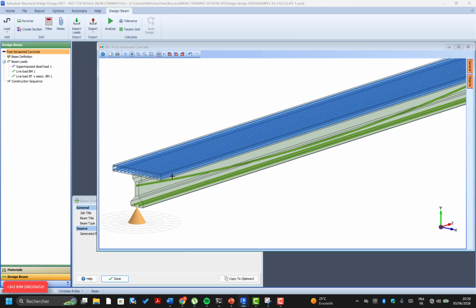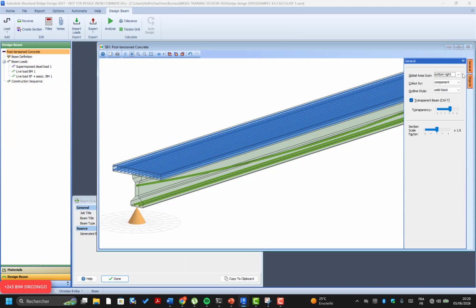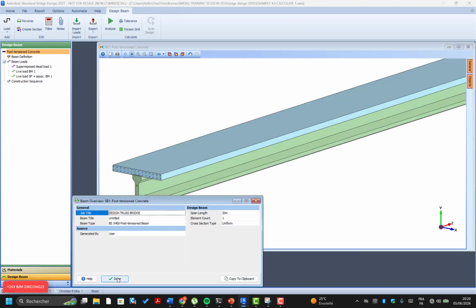Post-tensioning is a form of prestressing, and prestressing simply means that the steel is stressed, or pulled, or tensioned before the concrete has to support the surface load. So post-tensioned concrete means that the concrete is poured and then the tension is applied, but it is still stressed before the loads are applied, so it is still prestressing. This is what we are talking about and what I'll show you during this presentation.